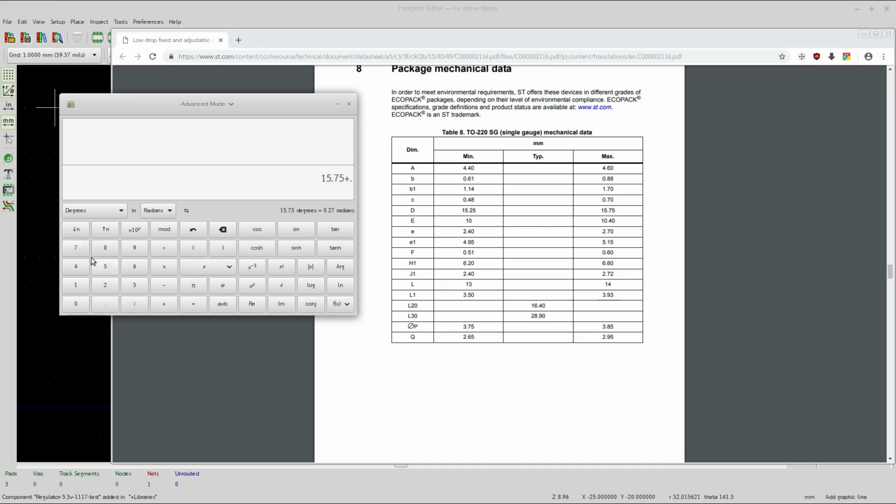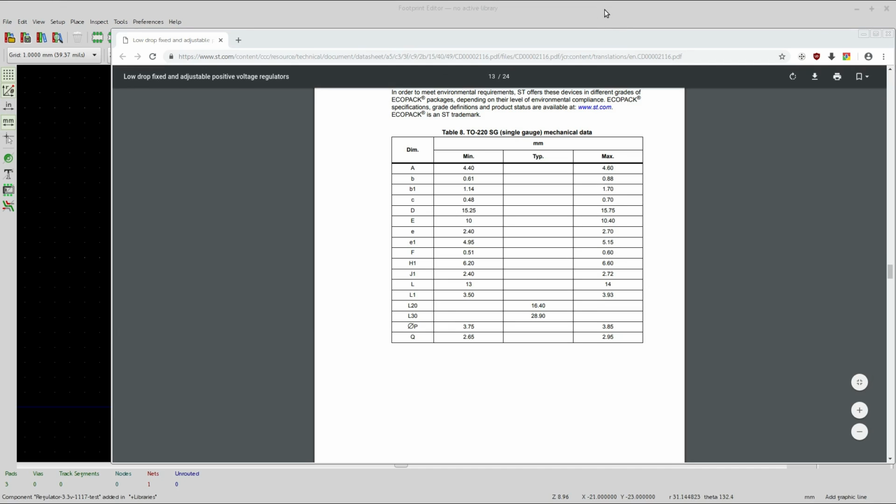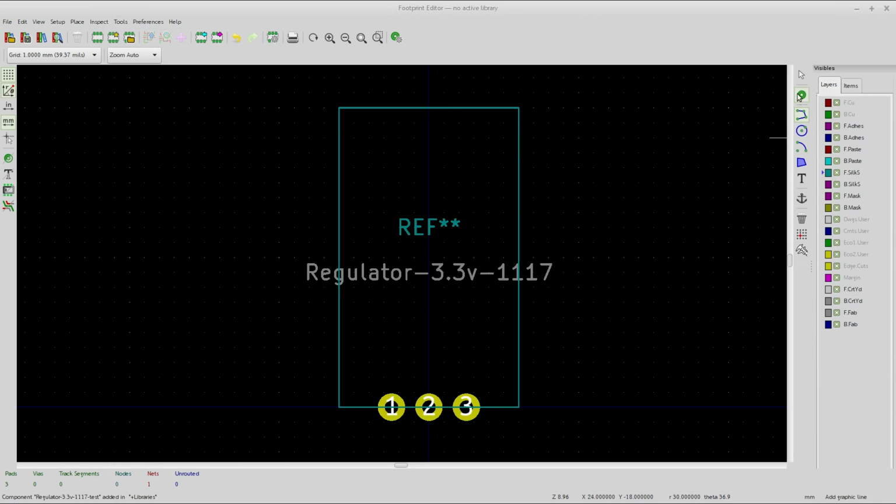And then, you know, 16.45, give it maybe another 0.5 millimeter or so of bend radius right there. So we're still pretty good at our guess, that we're about 17-ish sticking out to where the hole's got to be. So I know I said accurate and then I said ish, but that's kind of what we're left with here. So we'll come over here and we're going to place that hole from here because I think that's our next critical feature.